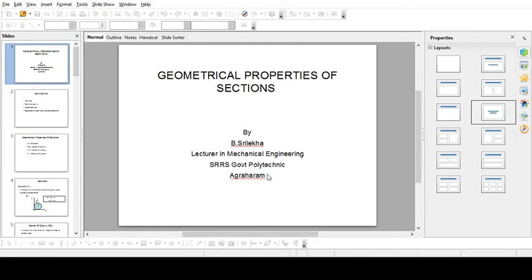Now coming to the y term. From here the distance is simply 80 by 2. We know that for a rectangle it is L by 2 and B by 2. So like that we get the centroids 50, 90 and 50, 40. Now how we get the central centroid, we will find.